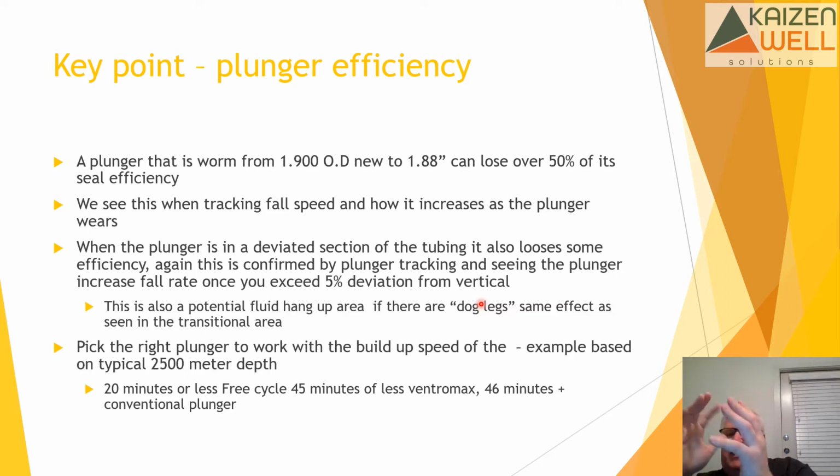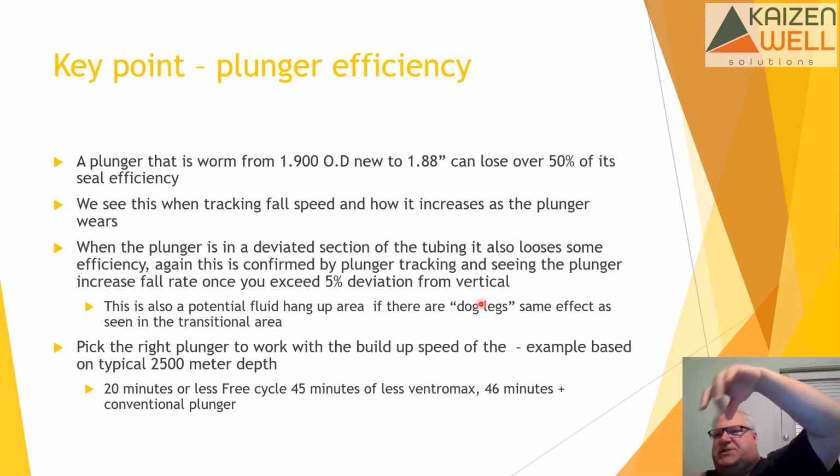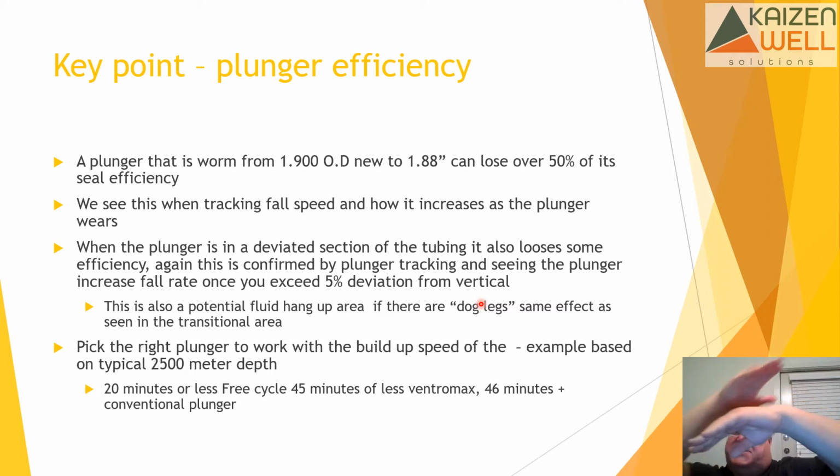You can hear them like they're rattling down and it's bouncing and it's really creating all sorts of extra turbulence and restriction as it's falling down the well. When it gets on its side, it lays flat on that dog leg and it just has a large bypass area on the top and that plunger will actually speed up and we see that all the time. So it'll have the same effect coming up.